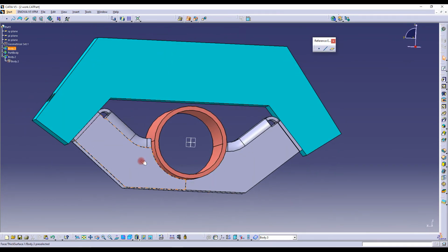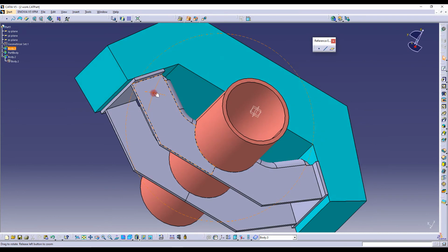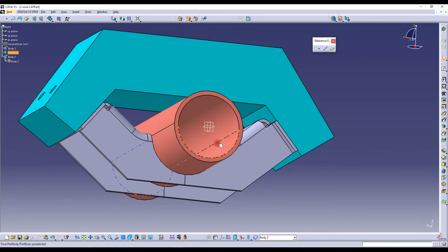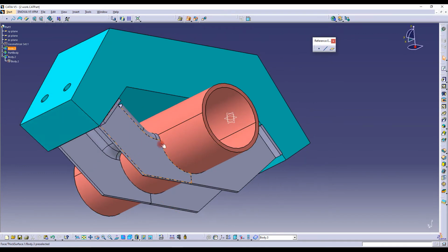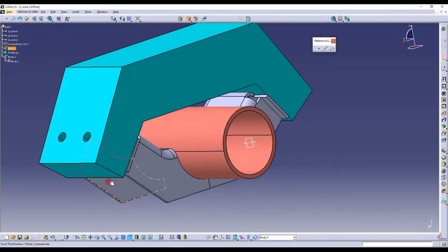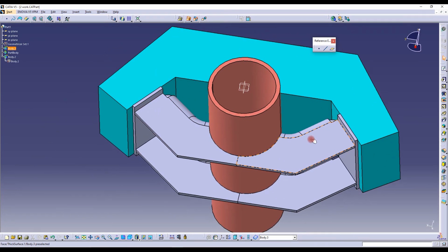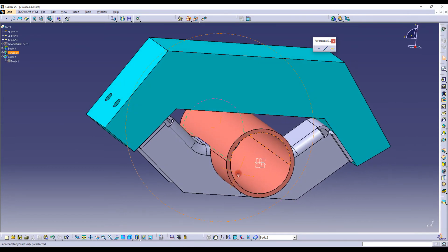So as you can see, the bracket is sitting nicely. It is mating with the two mating faces, and also it is having a good connection with the pipe. So it will be welded over here throughout for a rigid connection, and it will be bolted over here. So this is a combination of a form and bend bracket.